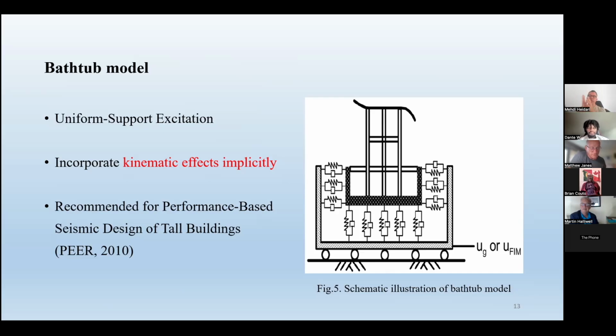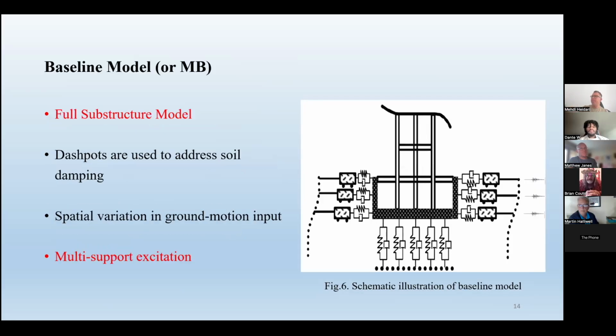So can we find something in between to not only be accurate, but also less costly in terms of analysis? They came up with this spring concept, and they call it the Winkler spring. That was probably the name of the person who invented it, in the 1800s, who replaced or represented the soil with a spring.